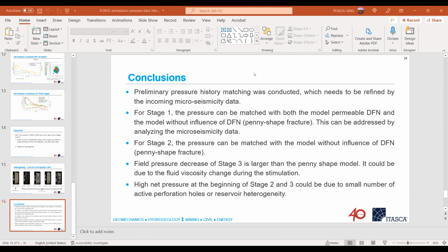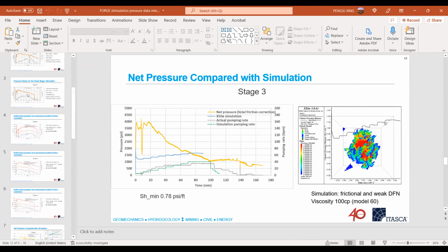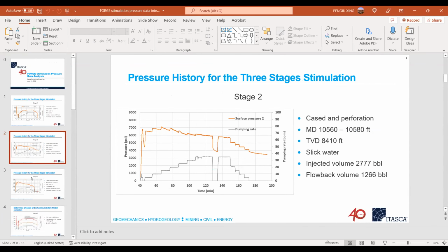Yeah, so my comment is what John just said. When you fracture from a horizontal well, you get near wellbore tortuosity. Fracture tends to initiate longitudinally, and then it's going to have to rotate 90 degrees to become transverse. That creates a pinch point near the fracture. And what that does is it can create an additional delta P, so that even if you account for the perforation pressure drop and the wellbore friction, you still might be estimating a number that's a lot higher than what's actually the pressure in the fracture. And to make it even worse, that tortuosity changes over time. As the fracture grows, it might grow back into the well and go away. So you have this additional delta P that we know is there, but we don't know what its magnitude is, and we know that it can change over time.